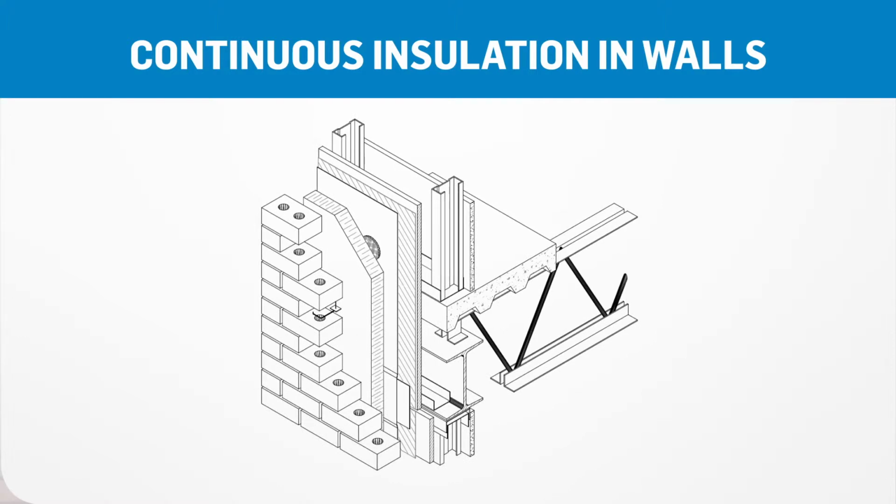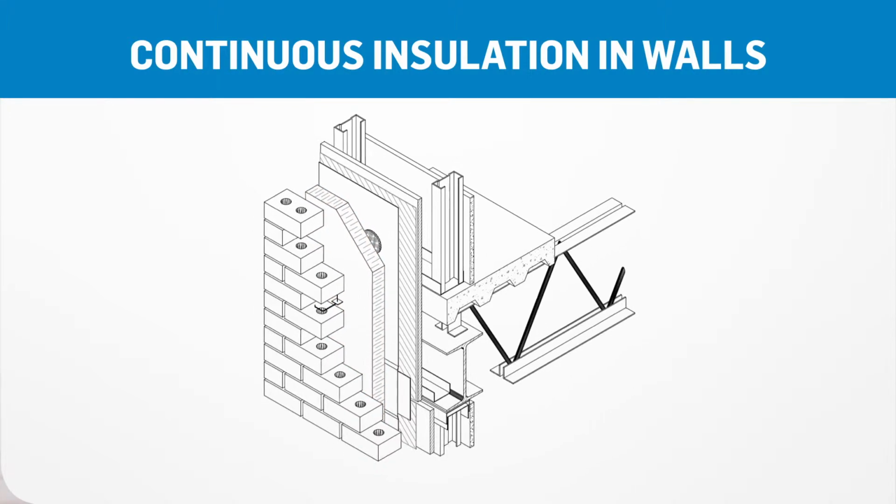On a roof, it will be visible. The thin layer of snow will remain intact. Now, it's not that common to see a thin layer of snow staying on a wall to illustrate thermal bridges, but the concept is the same. If the exterior wall suffers from significant thermal bridges, there will also be energy losses that may not be visible, but will have an impact on the building heating or cooling bill. In an assembly like the one shown here, the concrete floor is not extending to the outside. It is rather interrupted by continuous exterior insulation that breaks the thermal bridges. Thermal leakage throughout a structural component is mitigated by the presence of external continuous thermal insulation.